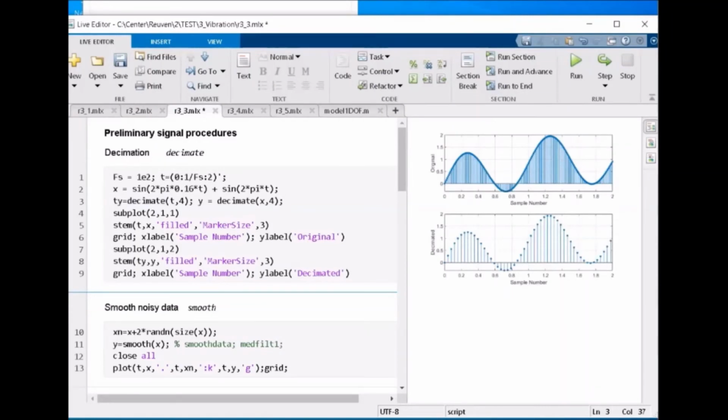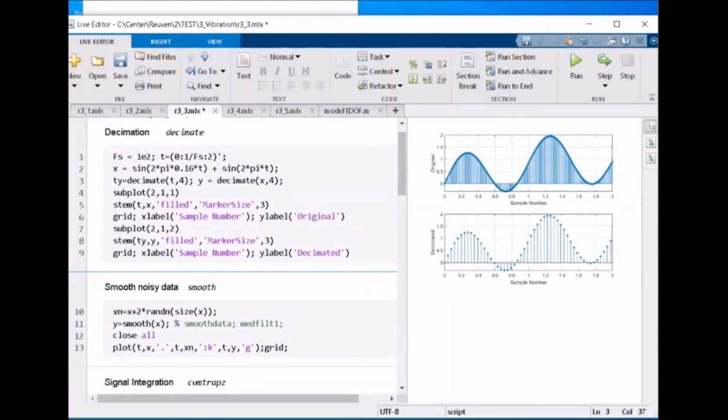The first subplot shows our original high number of samples. Here in the lower plot, we have the same plot. You see, physically, we have the same. We don't need such a large number. We get the same results, just leaving only each fourth point in the sample. Okay, it's decimation. Very important for some kinds of spectral analysis.